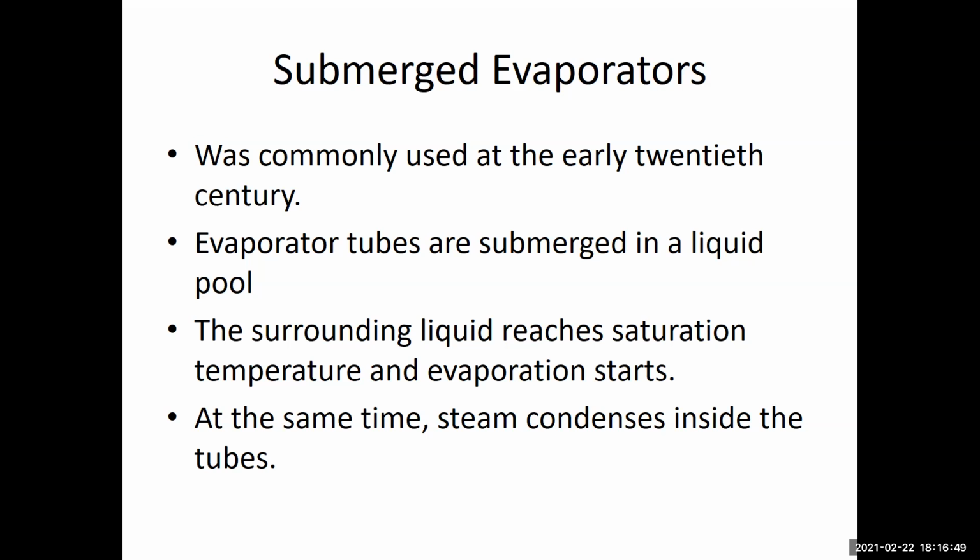and then evaporation will start. It's not like when you have a tube bundle and you are spraying a thin film. Suppose there's a sprayer here, like a shower, and this shower is spraying seawater on a hot surface. A thin film is going to form here around the tube, and it's easy to heat the thin film to saturation temperature, and then evaporation will start.